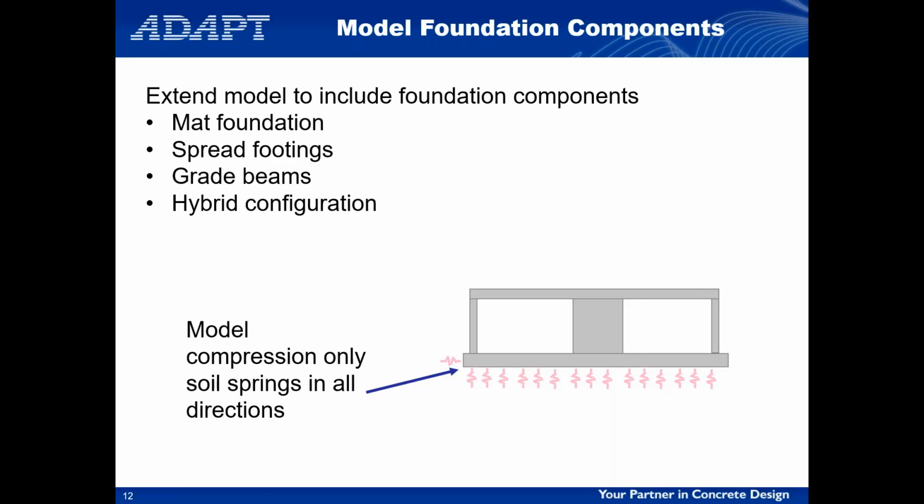So now we're going to move to the foundation, because one of the things that I've heard consistently from our clients out there and just general structural engineers is that if you're just using either Floor Pro or other finite element slab programs, then there's the challenge of how do you take the redistributed loads? Because you can't just run an RC slab design, because that doesn't account for the stiffness and redistribution that the post-tensioning offers in your podium.